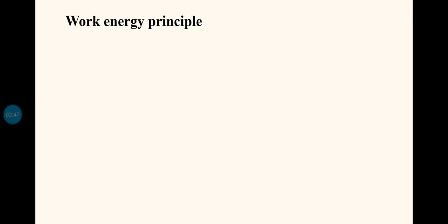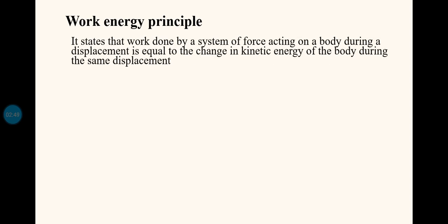Now we will move on to our topic, that is the work energy principle. It states that the work done by a system of forces acting on a body during the displacement is equal to the change in kinetic energy of the body during the same displacement. So due to the cumulative effect of a system of forces, assume that the body is moving along a particular direction. Then as per the work energy principle, the work done by the system of forces will be equal to the change in kinetic energy. So we can equate work done to the change in kinetic energy of the system.